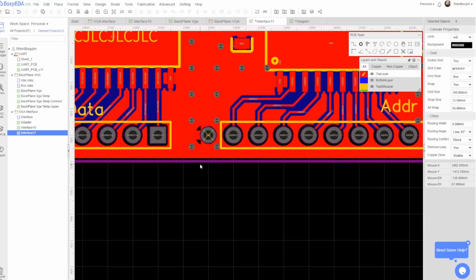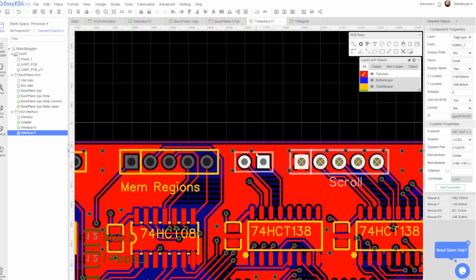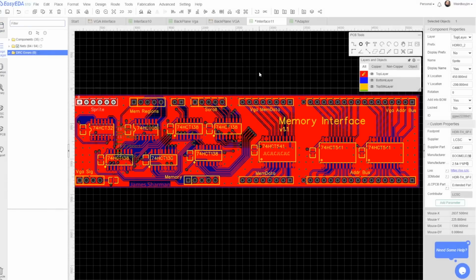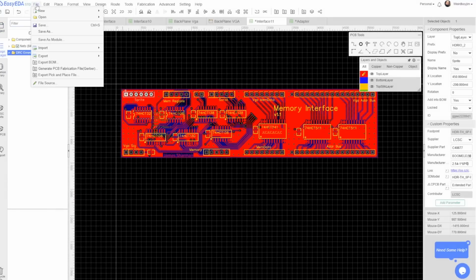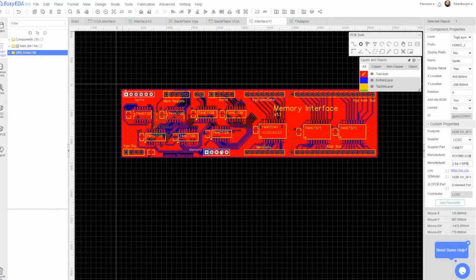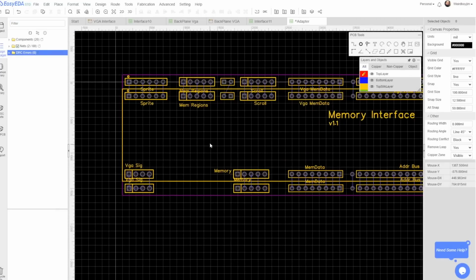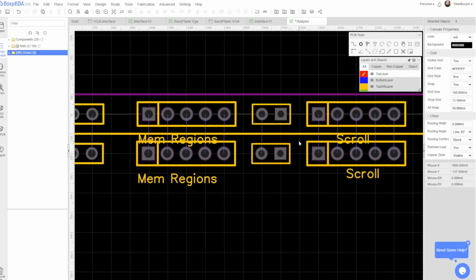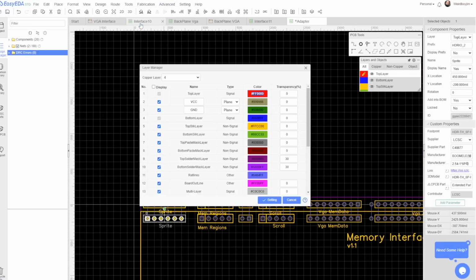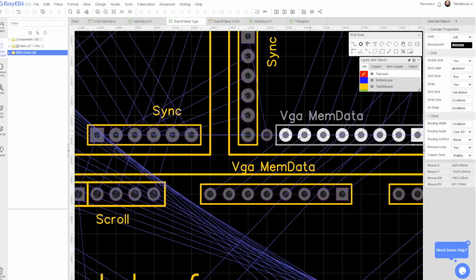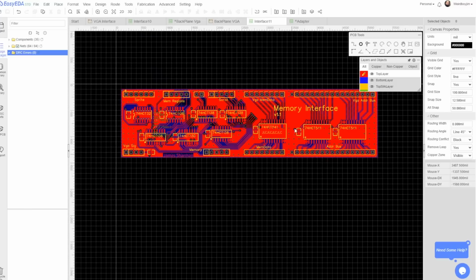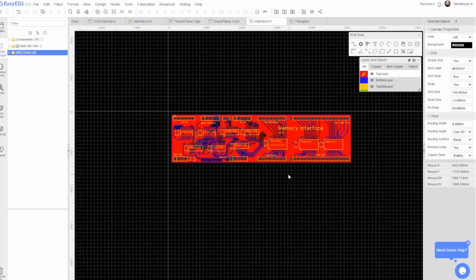Don't like that. Slight enough that it didn't cause us a significant problem at least. Added a couple of ground points there that we put onto the PCB and didn't use. I was worried these address lines were too far from the nearest ground connector to the backplane.